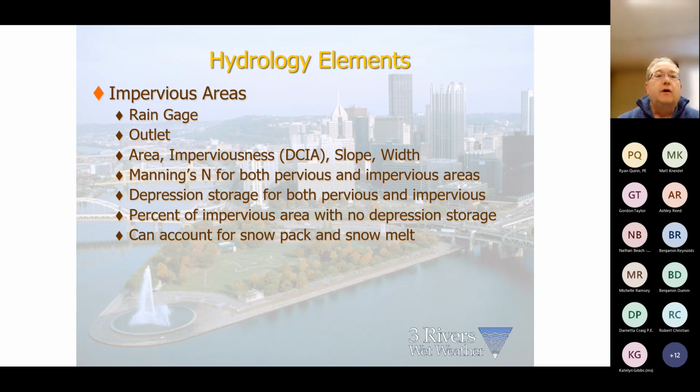Right. So don't we want to keep it as is? Yeah, the methodology, I definitely would not change. What I'm saying is part of the calibration, and I agree with what Sam just said, the infiltration would not be my initial parameter that I would look to modify. There are other parameters that are part of your subcatchment representation that are much more sensitive and impact the flows greater. That's more on your impervious area side that I'll talk on in just a second. Those are usually your primary factors.